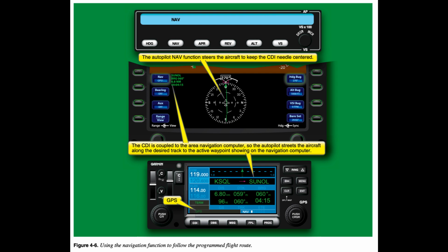When combined, use of the FMS and the FD/autopilot's navigation function result in an automated form of flight that was formerly limited to very complex and expensive aircraft. This same level of avionics can now be found in single-engine training airplanes. While it is easy to be complacent and let down your guard, you must continuously monitor and stay aware of automated systems status and function and the track of the aircraft in relation to the flight plan and air traffic control (ATC) clearance.